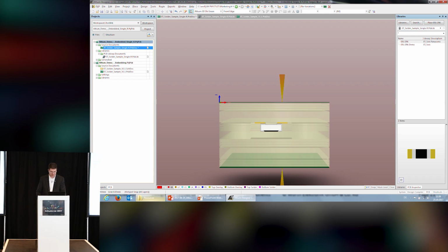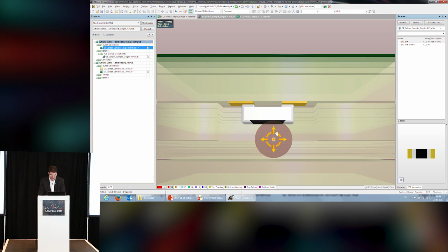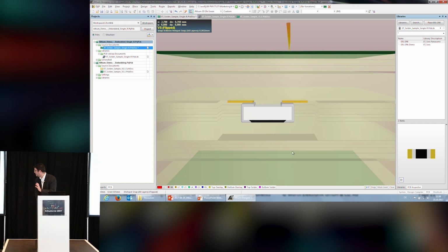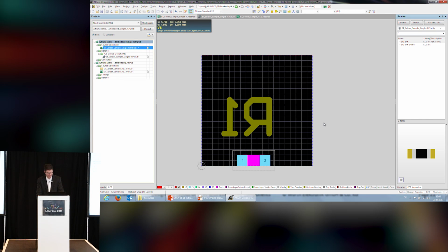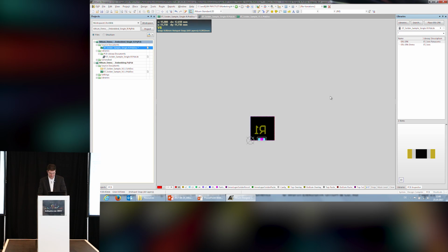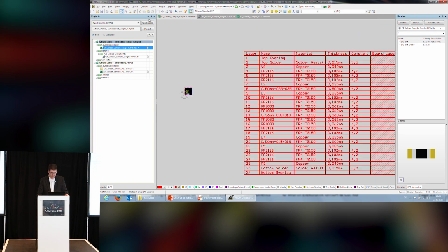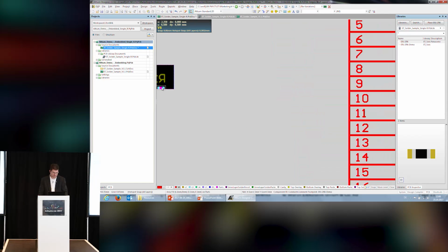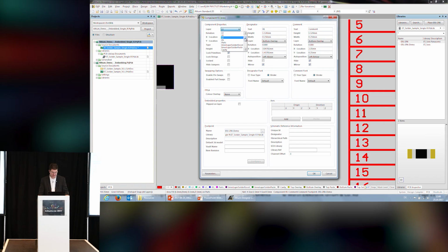So again, let's switch to Altium. And we already see it here. When I move it around a little bit, you see the hints that this cavity is being created by Altium. That's why I moved the component to the edge, for you to see that there is a cavity, so that you see the component sitting inside and the space you need for that cavity. When we go to the 2D mode, and I zoom out a little bit, I placed already the layer stack inside. So now, based on that component, we see this. And let's switch back. I just move the component to the outer layer again.